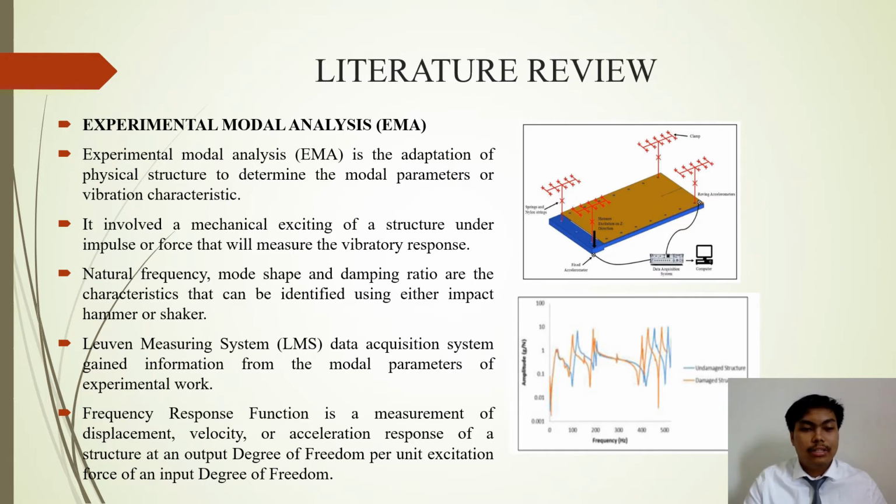Frequency response function is a measurement of displacement, velocity, or acceleration response of a structure at an output degree of freedom per unit excitation force of an input degree of freedom. The figure on my right here shows past research where experimental modal analysis is used to obtain the frequency of the undamaged and damaged structure.